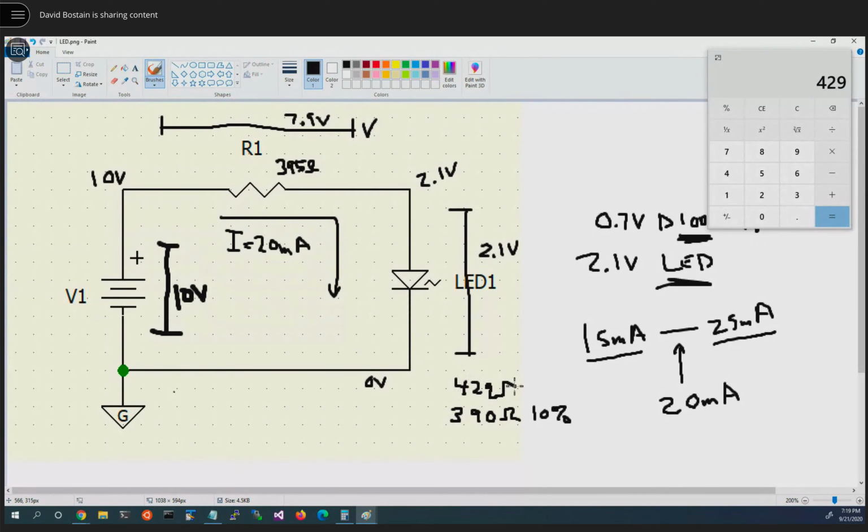It's possible that it would have that large of a value. Larger value of resistance, less amount of current. So you would check this value to see whether or not it's going to be bright enough to be turned on. We also could take 390 and subtract away 39. We get 351. Less resistance, more current. So this is the guy that potentially we want to check for its power rating.